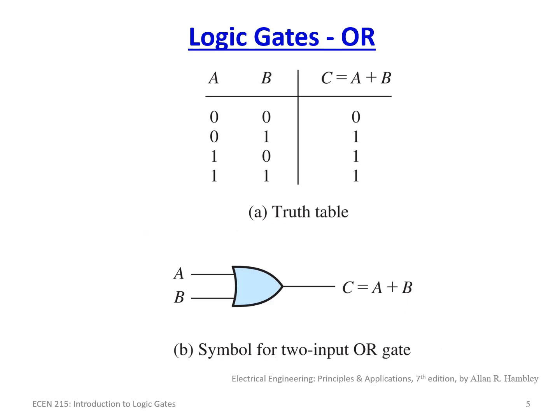OR gates. Well, now we're implementing the function A or B. And that's represented by this symbol here. And that represents the OR gate. And so simply, if you wanted to have A or B, its truth table being this, where F is equal to 1 when A or B is 1, you would use this symbol to represent that.